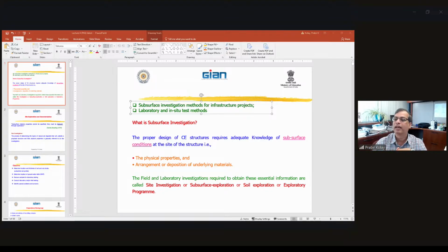It's very common over here. It depends on the availability of the equipment. A lot of DOTs over here in Illinois, in the US, are using CPT values, and there are also correlations. But in most cases, the SPT value is easy.